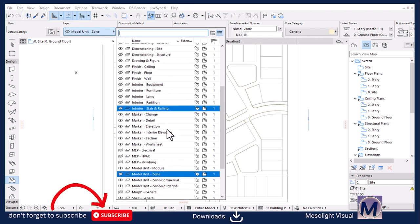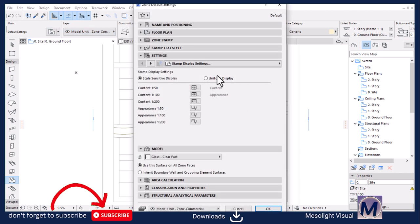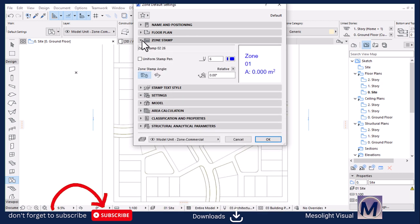So I'm going to activate the layer for commercial. And then let's open the settings and see what we can do there. Under the settings, there are plenty of things here that are unnecessary for this exercise. So I'm going to delete everything except the zone name. And then let's move up to the zone stamp, to the floor plan.